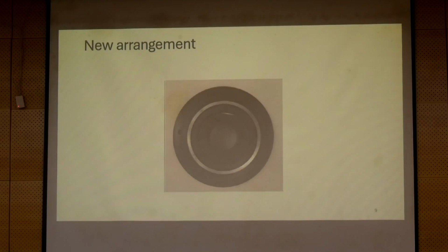If you want only static eccentricity fault, then the bushing on the inside will have 0 offset, but the bushing on the outside will have some offset. If you want only dynamic eccentricity fault, it will be the other way around. Okay? And when you want a combination, both the bushings will be offset bushings or eccentric bushings. Okay? So this is how we can achieve different combinations.